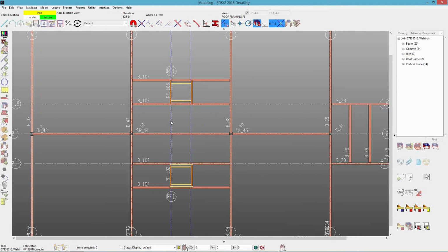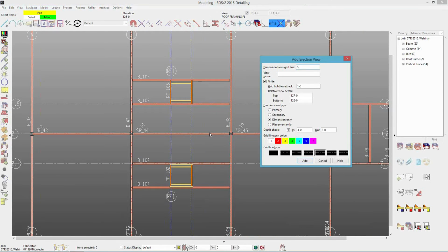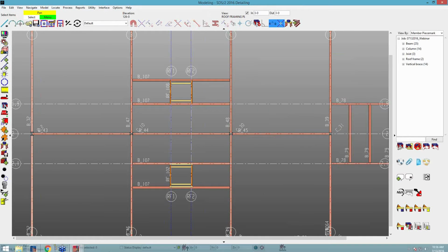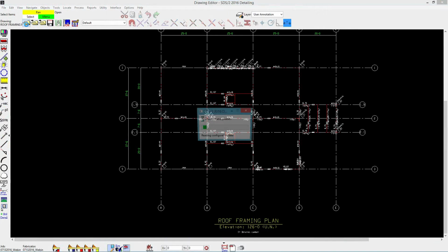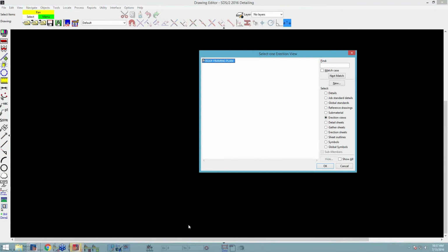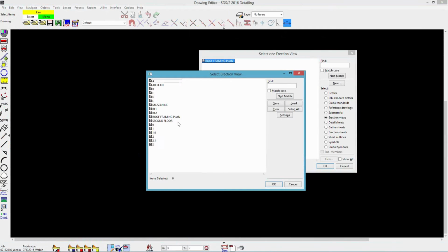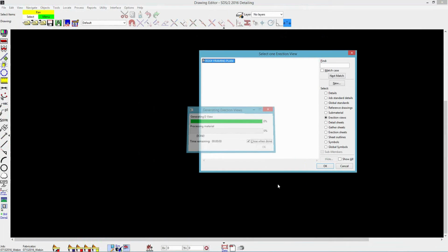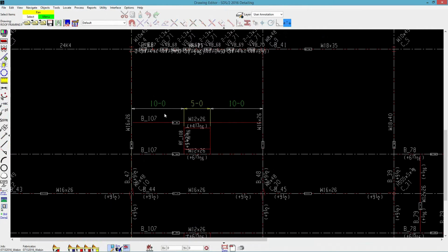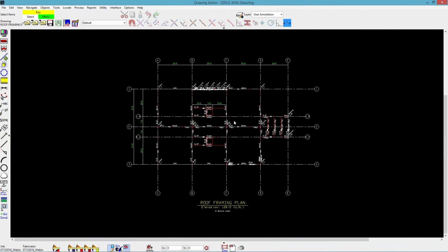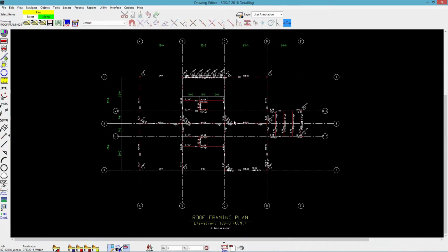And then I'm going to go ahead and offset that 5 feet. Okay, make sure my erection view wasn't left open, and then I can detail that again. And then there we see with those dimension only, we'll get nice dimensions for our roof frames as well.